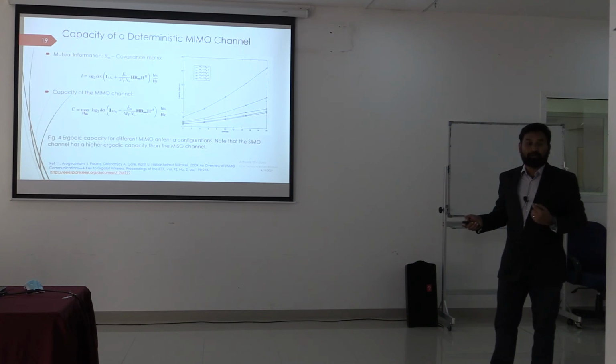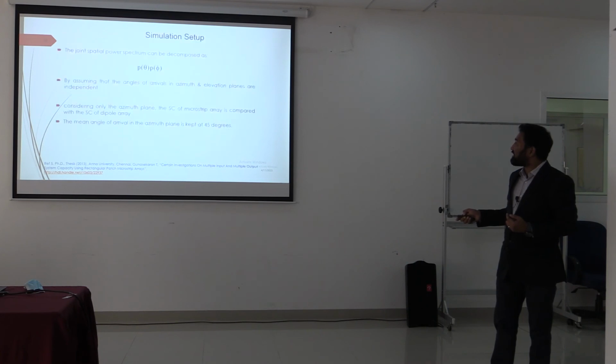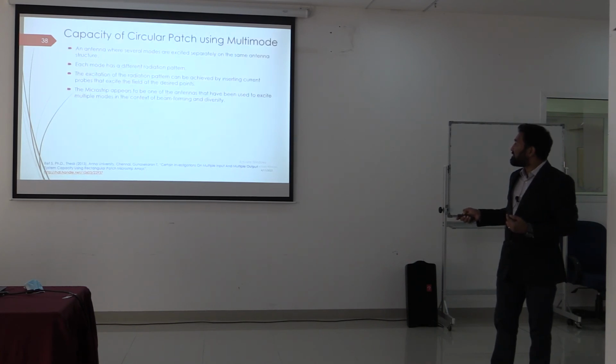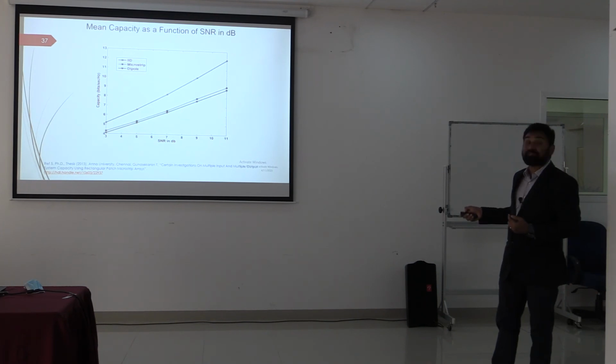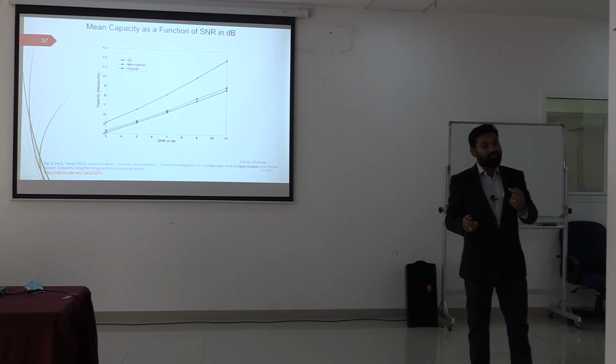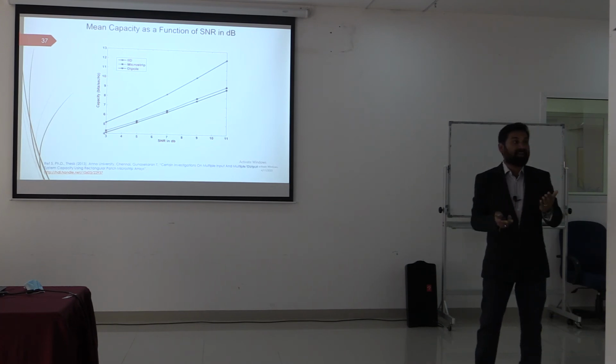So we developed our own antennas. We proved that for the random nature, when you select suitable microstrip antennas, you are able to provide the same performance with respect to your microstrip or dipole, which will give almost the same antenna characteristics with respect to the SNR. The capacity is also the same. So we have to select the channels in a proper way that could bridge the theoretical approach to the practical approach, and we can balance both things.